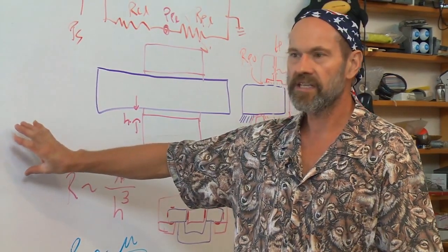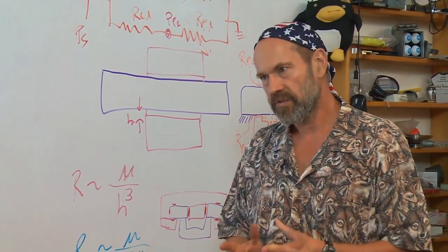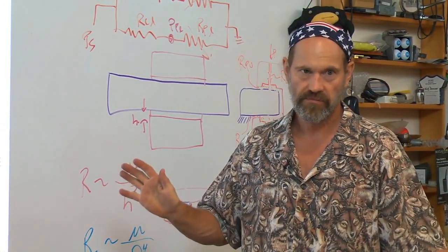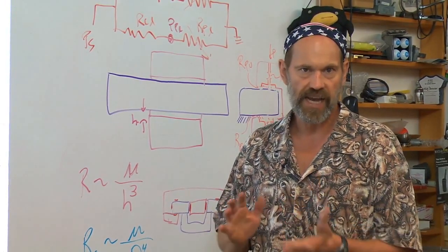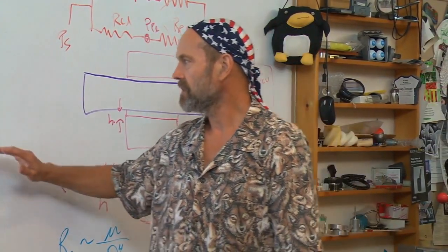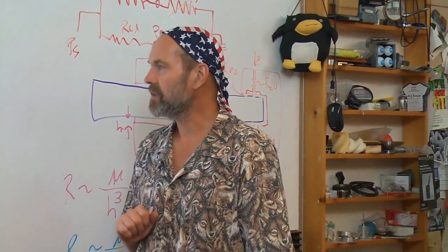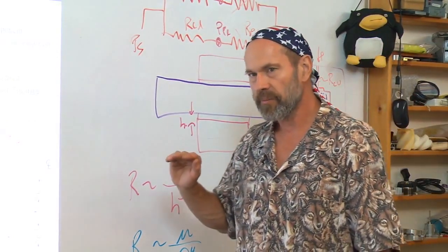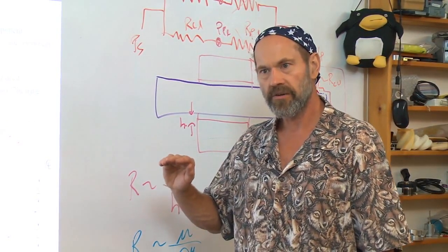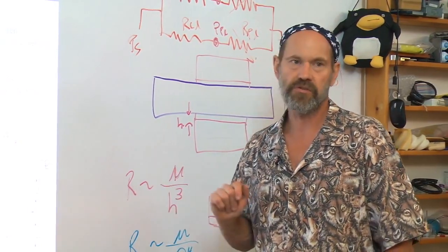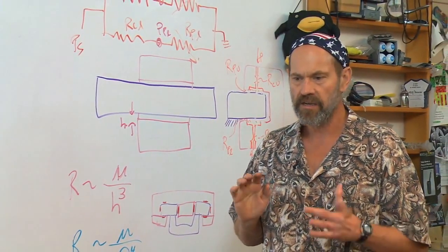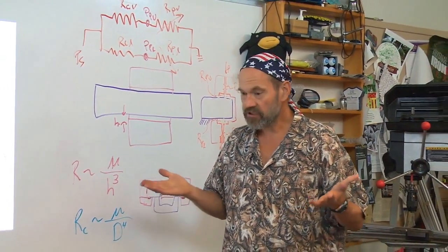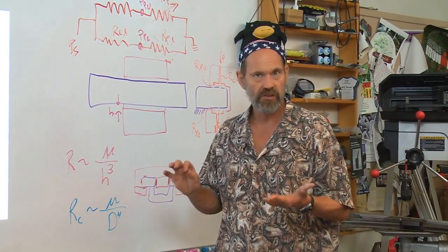These bearings are used quite extensively, actually, to support shafts of machines that have to run under very high loads continually. For example, compressor shafts for natural gas pipelines. They're often run using magnetic bearings. For super precision motion, linear and rotary, where else would you use these kind of bearings? Where else do I need the highest of high precision where the smallest little error, even on the nanometer level, starts to cause me problems?